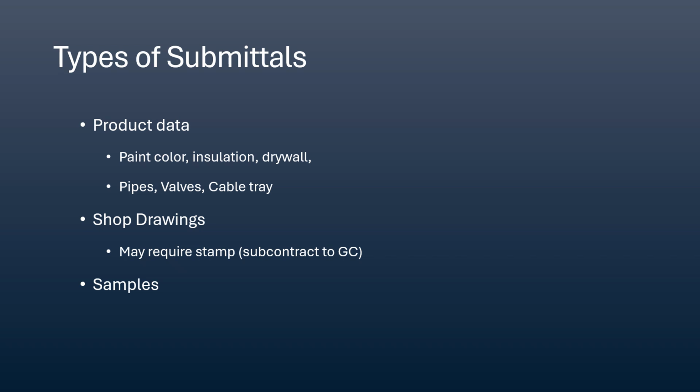A common example of this is maybe anchor bolts. Going back to our pump, if the pump requires a very specific type of anchor bolt, there's going to be a structural engineer that will design those anchor bolts. They're going to provide calculations on how they got to their design. They're going to submit that with the pump shop drawings, the pump submittal, and those designs, those calculations have to get approved before we can purchase the pump and before we can purchase those anchor bolts.